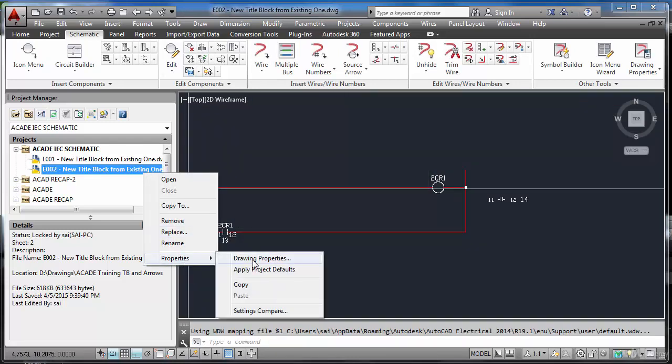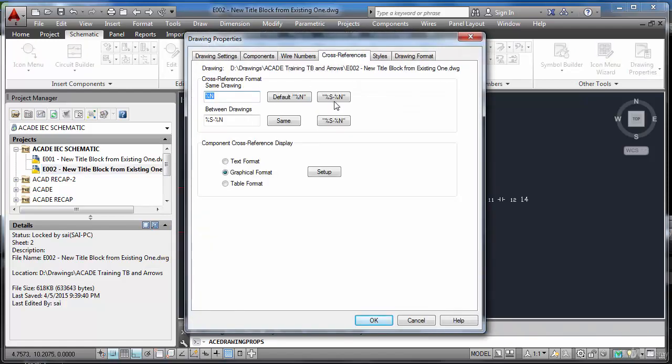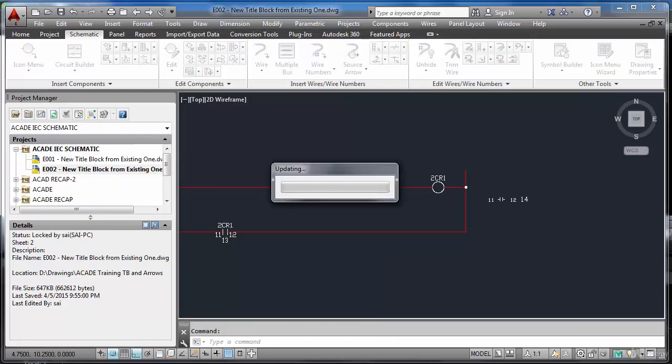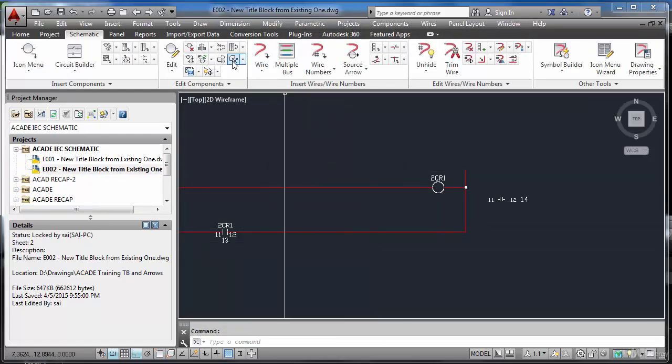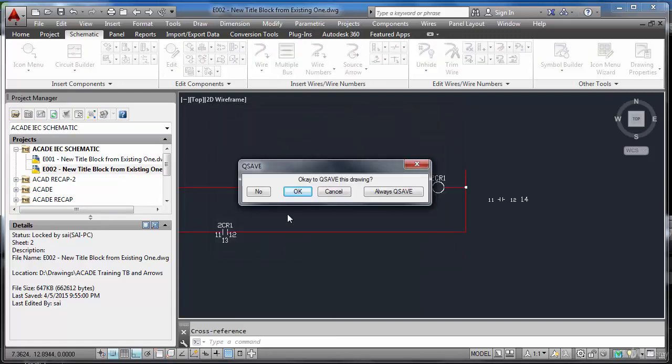In fact, if I want to change that too, it is possible. Earlier it was just a default numbering, just those numbers represented on the vertical axis. Now if I click this, yes also comes. Yes means sheet number plus this line number. Both are here. And if I again want to put it some other way, like this, this is also very much possible. Update, active drawing, okay.